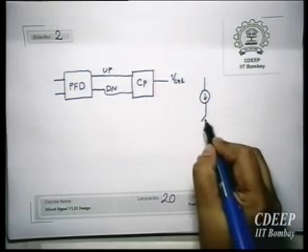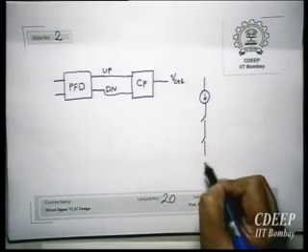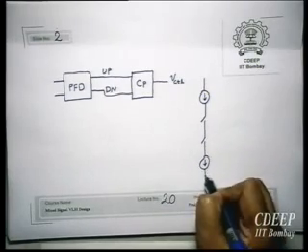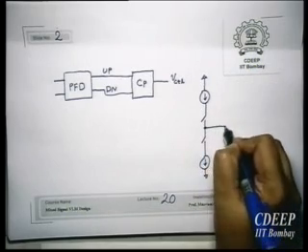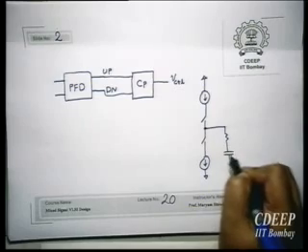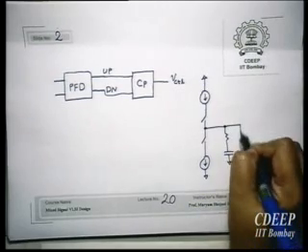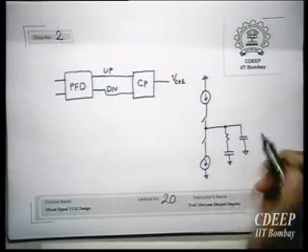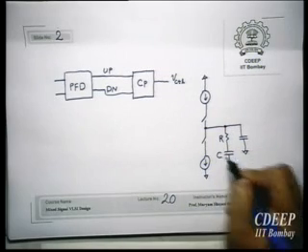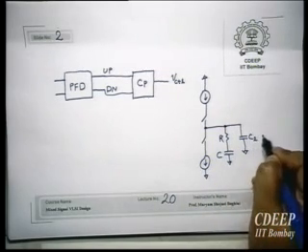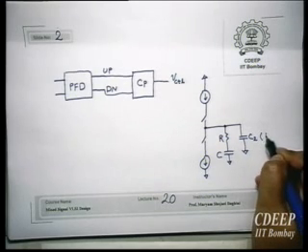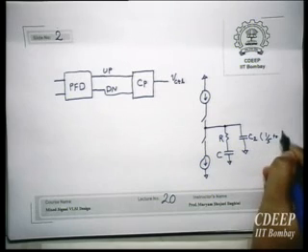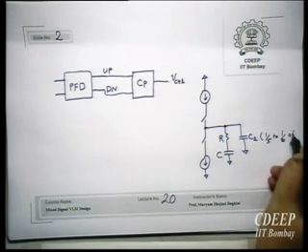There are two switches, and these switches are controlled by up and down. So this was practically the filter. And this C2 we decided to choose much less than C. For example, it can be 1/5 to 1/10 of C.